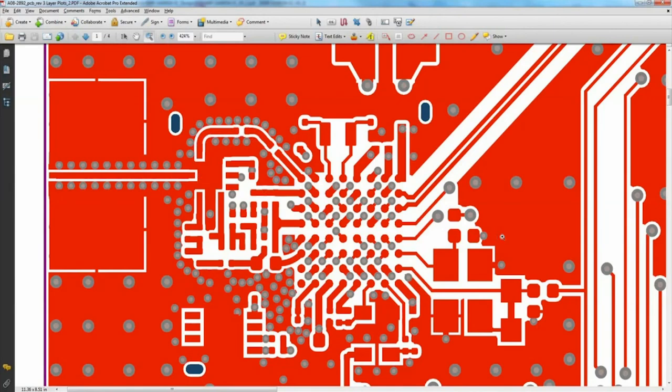So you want to separate high-speed signals from low-speed signals and digital from analog signals, for example, by going at 90 degrees instead of parallel. And to minimize crosstalk, doing the same. So avoid vias in differential traces like we have here. If it's not possible to avoid them, then use vias in both traces or compensate the delay also in the other trace. And finally, I'm just going to mention briefly clock distribution.